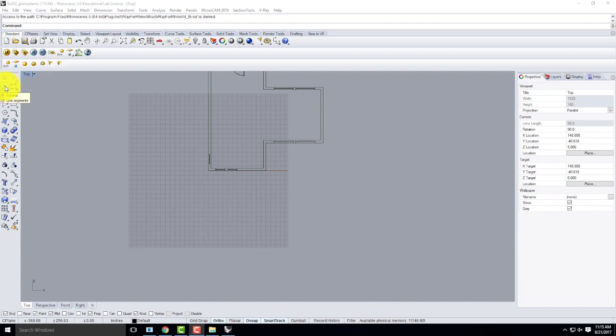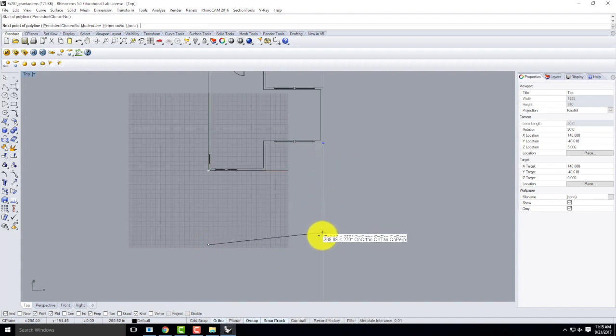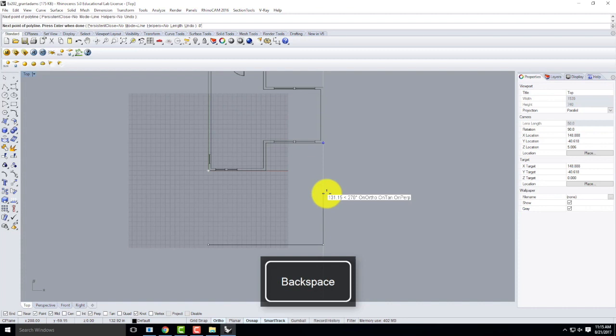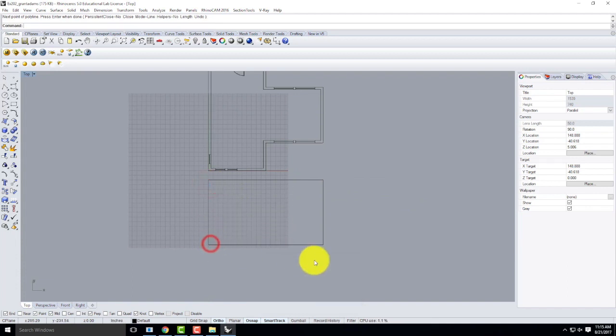So we'll draw using a polyline tool. I'll draw a baseline down here a ways. It doesn't matter how far away it is from the building. That is the same length as the building. Notice that I used my object snap to pull those 2 lines. I want to specify a height, so this would be the height of the wall. I'm not going to worry about floor plate and floor assembly or roof assembly. We're just dealing with the wall right now, so we'll do 8 feet. So I'll type 8, followed by the apostrophe for foot. There it is, and I want it going in that direction. Then I'll draw straight across, and I'll draw back down to right there.